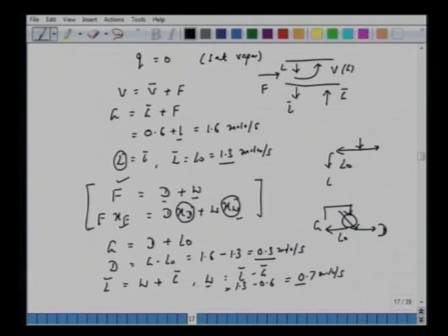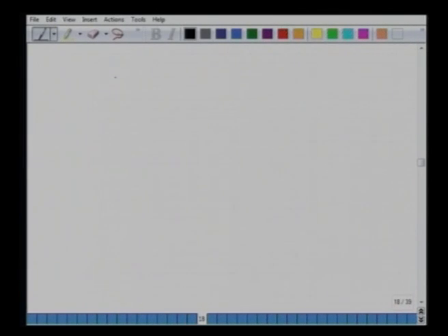So essentially now we have all the quantities. If you substitute in these equations, F is known, D and W we have calculated, XF is known, but XD and XW are not known to us. So this equation we are still not in a position to use. Okay, what else can we do? Now we can write down the operating line equations.